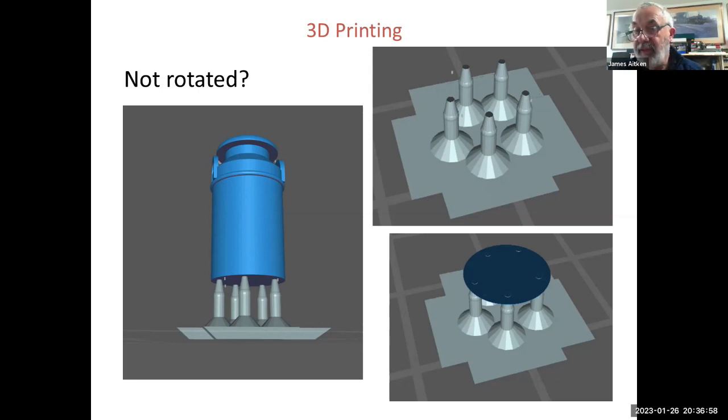And there's nothing holding the middle of that ring in place. Now, I could have put another support in, but even so, you've got a layer of hard resin, or hardish resin, that's 0.05 of a millimeter thick, the first layer that's made, and some significant gaps between the supported structure. So that is not going to work as well as the previous mechanism where you've tilted the model over, where it's built up much more gradually. There's no sudden parts that suddenly appear.